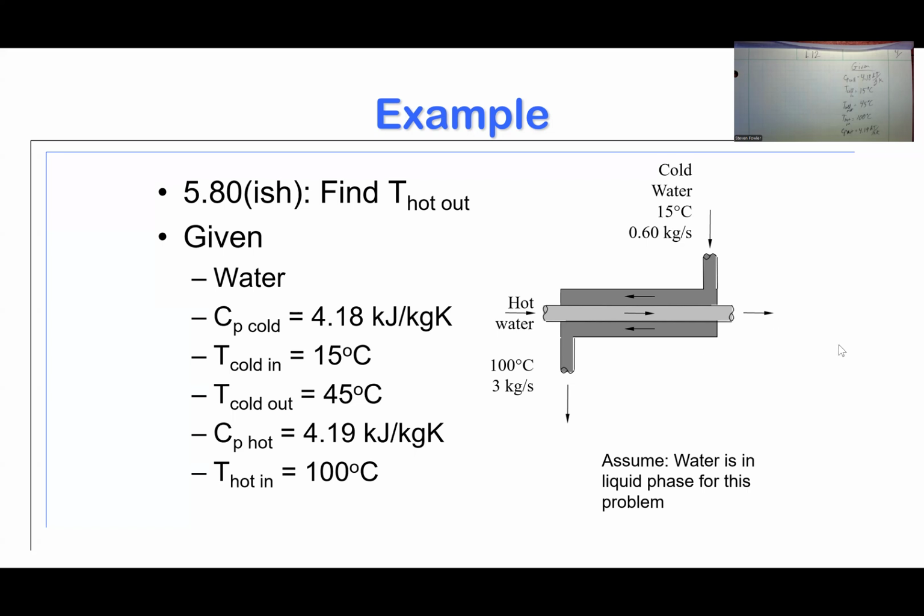Double pipe is a common type of heat exchanger. It's very easy to manufacture. You just take one pipe and you lay it inside of another pipe. And again, the counterflow mechanism means we're just going to flow the fluids in opposite directions. An advantage to this is you get kind of a more gentle cooling.